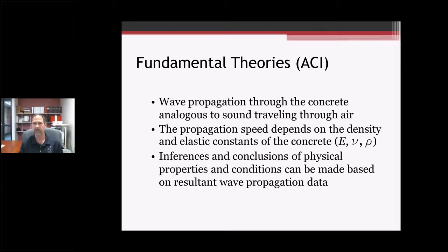The idea is, these stress waves that we're putting into the concrete structures are going to bounce off of the bottom of the slab or the other side of the wall, or some other anomaly or defect within the slab itself. So if you're close to the edge of a slab, that sound wave is going to bounce off of the edge of the slab and maybe the bottom of the slab also. So sometimes you want to stay away from those edges and interfaces like that. So just always remember sound traveling through air.